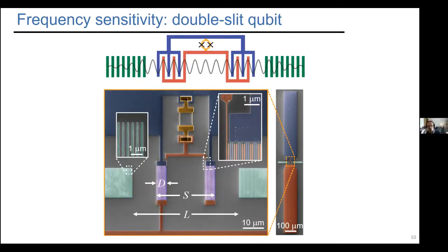Yeah, so the proposal that I cited is for using 3-way, 4-way mixing of the junction to do some parametric gates between the acoustic modes. That really requires distinct energy differences between the modes you'd like to couple to each other, and that's really not natural in a Fabry-Perot type cavity where the modes are evenly spaced. If you'd like to do that, you basically have to engineer a frequency-dependent delay to make your cavity mode spacings different, and we have some ideas for how to do that.